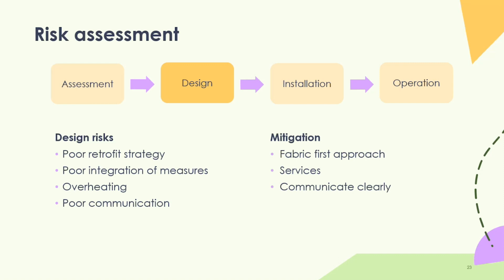So if you've got a difficult to treat property, for example, there may be fixtures and fittings of a certain design that might be difficult. So for example, Cornish homes, the roof verge fittings are quite difficult. So making sure that you're accounting for that and what specific services or specialists you might need to help with the installation of EWI where you've got those difficult roofs.